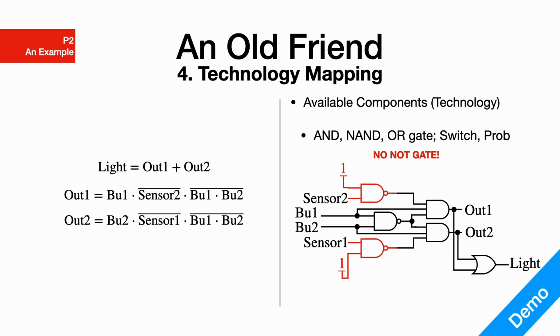This replacement unit would work exactly the same as the NOT gate, and this is what you might encounter, although very unlikely in this particular manner without a NOT gate. But this is in fact something that you would probably encounter in technology mapping. Sometimes you have fewer components available to you, and sometimes you have more alternatives to choose from.